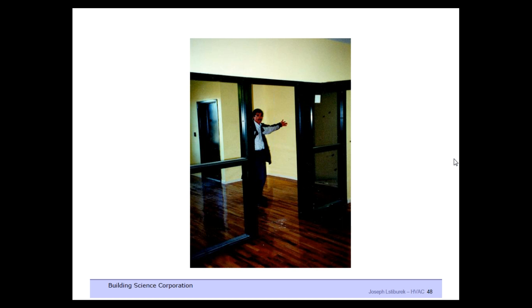It was a dream of a number of us over the last 30 years to be able to put our elevators in vestibules. Whenever we put them in vestibules to compartmentalize the building from a stack effect perspective, occupants tend to defeat the best engineer by leaving the doors or prying the doors open. I've come to accept the fact that this will probably not occur in my lifetime, and so from an engineering perspective, it's a desirable thing to have, but from a constructability and occupant perspective, occupants don't like it.